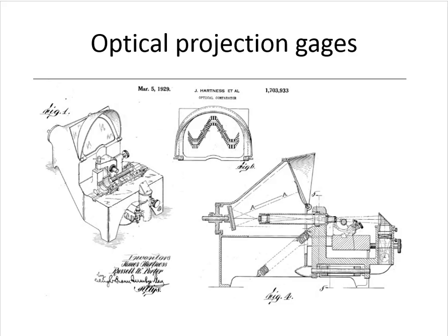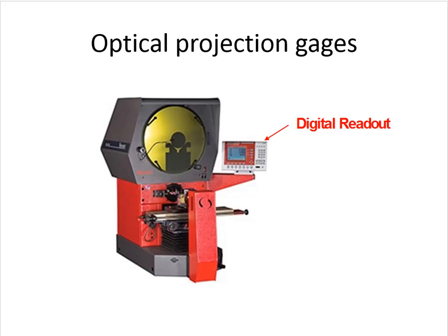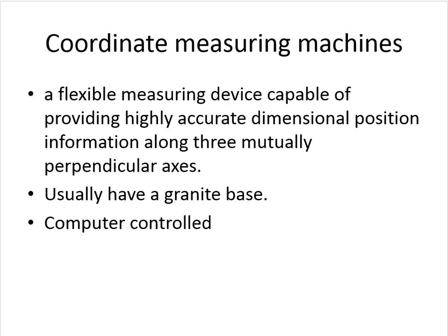Here's a good one, an optical comparator. They also call that a shadowgraph. It blows up the part into a big projection image. Then you can have a digital readout to measure how far it goes across. That's a very handy tool for measuring radiuses, contours and diameters.